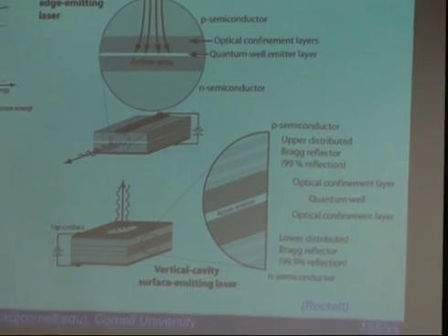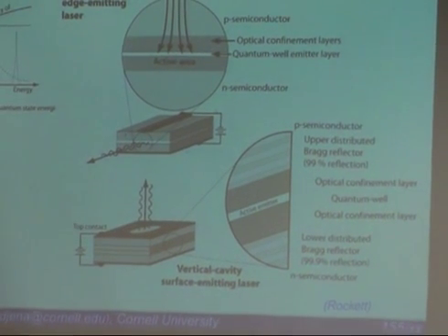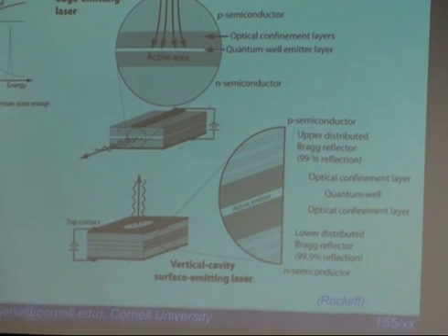And the way that you do that is basically the mirror here is basically a periodic grating of semiconductors of different refractive indices. I think you know that if you have a periodic grating of something, if your light is going through and the Maxwell equation sees the refractive index is changing periodically, right? It will gap it, and basically you create a gap for that mode. Just like electrons going through a crystal, and you see a periodic grating of atoms, you have a band gap now, right? That's what happens whenever you add periodicity.